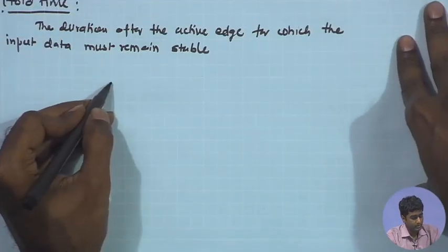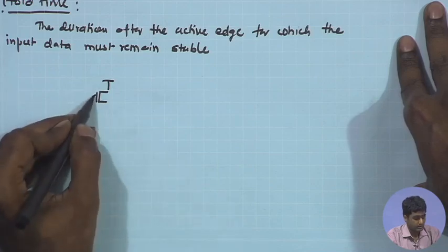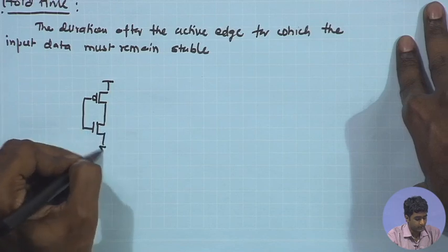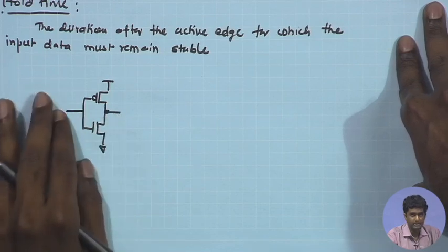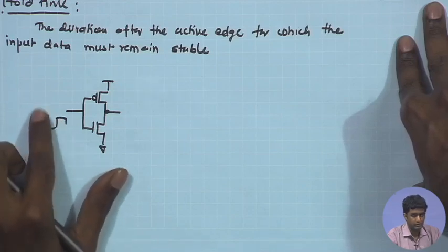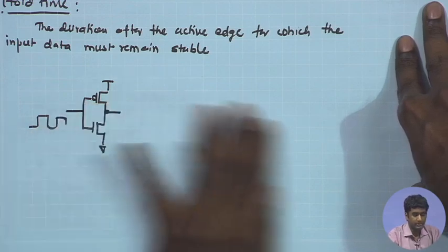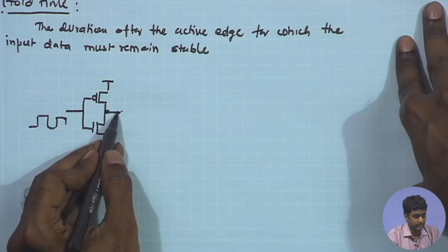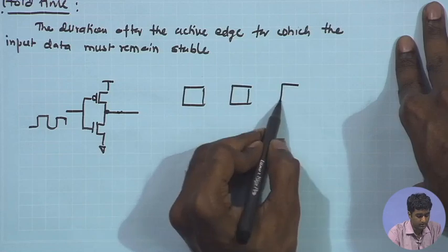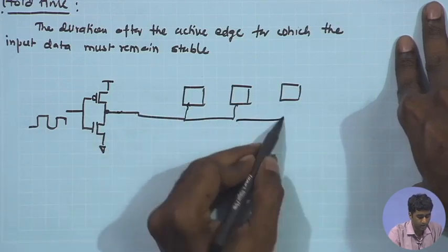So, rise time and fall time of the clock are going to be controlled by the buffers or the inverters which are driving the clock. Ultimately, as I said, the clock will be coming from some source having the signal 0 to VDD going in, and you may have a single inverter driving multiple transmission gates. So, a single inverter may be responsible for driving the clocks of multiple flip flops or multiple gates. You can have a single clock input going to multiple blocks.